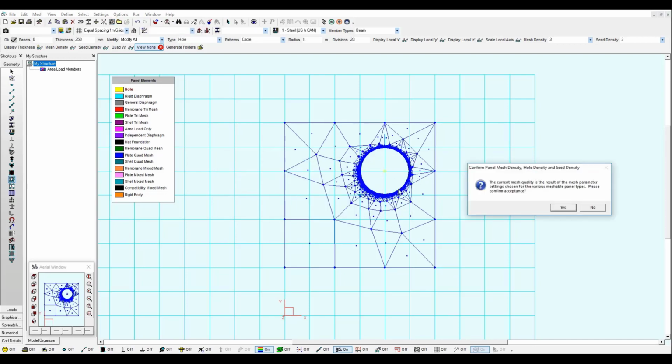As you will notice, this configuration can lead us to a warning message for elements of poor quality and potentially lead to less accurate local results. We will need to achieve a good ratio in each panel element. We can see the distribution of different sizes, how they are jumping.